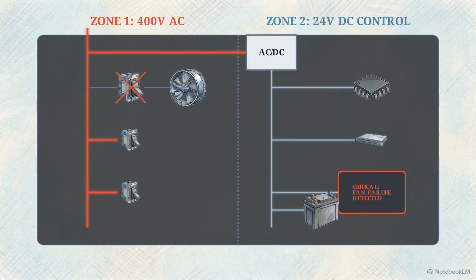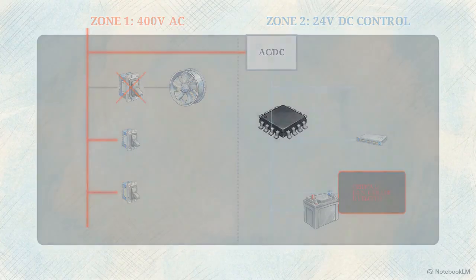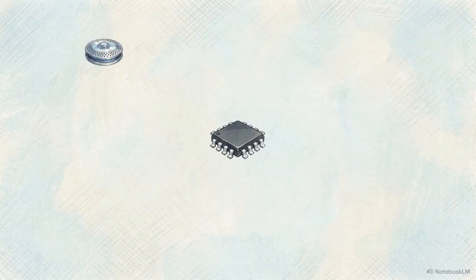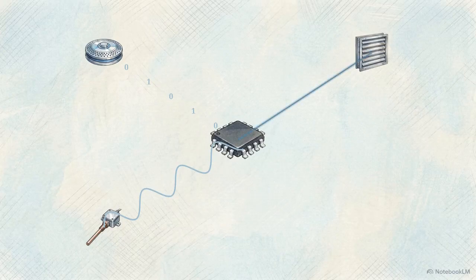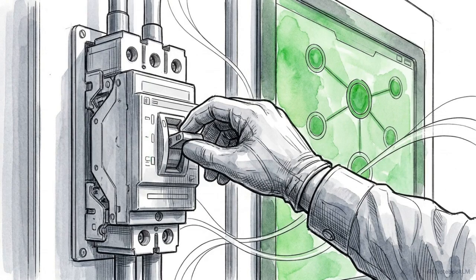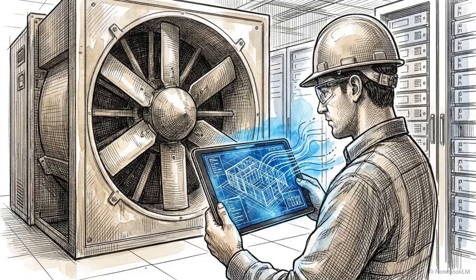All screen data traces to 4 channels. Discrete digital inputs report the status of smoke detectors or breaker contacts, while analog inputs provide a continuous stream of environmental measurements, like temperature and humidity. Relay commands execute digital outputs to move exhaust dampers, while detailed UPS telemetry arrives over the communication protocol network. This structural segregation ensures that monitoring logic persists even when high-draw mechanical components fail. Operators maintain the visibility required to diagnose the ecosystem from within a protected zone.